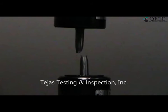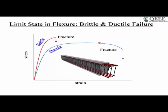But if steel fails first and concrete remains intact, unaffected, then what happens when the steel fails? Before it fails, it has to undergo severe deformation, and from this deformation, you get sufficient warning that can be useful to vacate the structure or to take any precautionary measure. So therefore, our goal always is to allow the steel to fail first, not the concrete. So we want our structure to be more ductile.